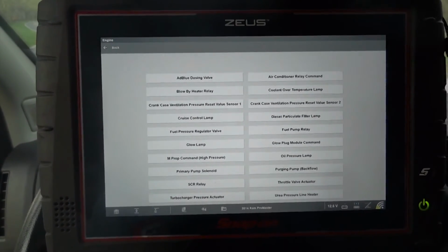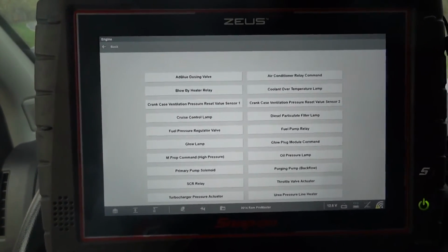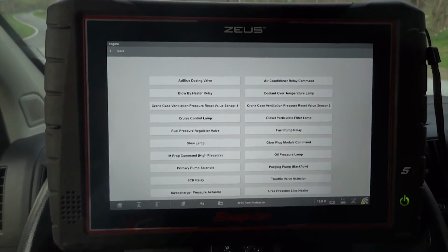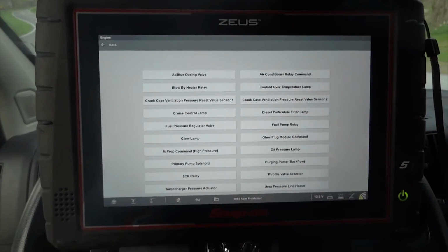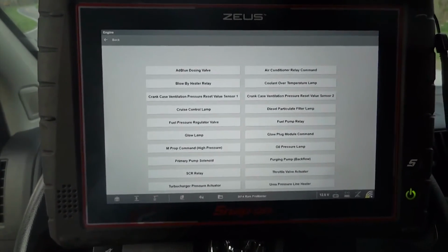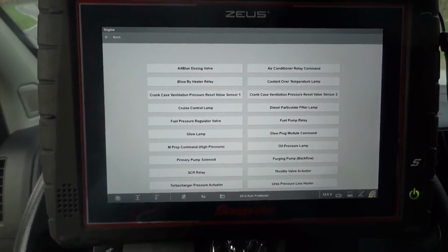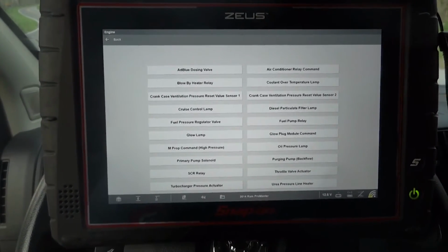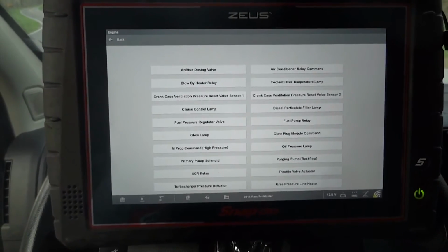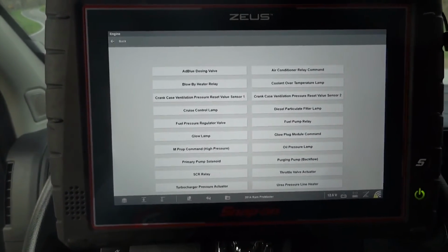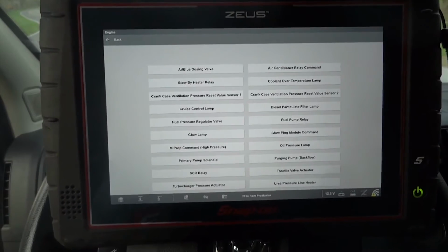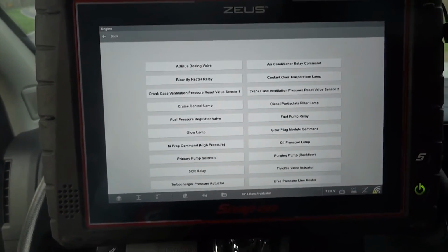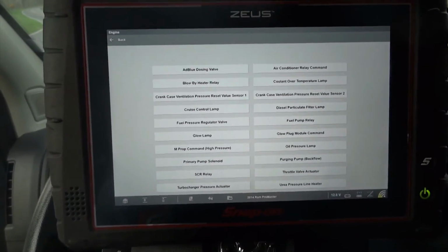I'm going to open the EGR valve at idle to see if our engine speed is going to change. If our engine speed changes, that will tell me that our EGR is working. The motor is definitely opening and closing. I mean, the valve is opening and closing, and we are diluting the mixture in the cylinder, because when you dilute the mixture at idle, the engine runs sluggishly. If it does, that should pretty much tell us that the EGR valve is most likely good. We don't have a clogged passage.